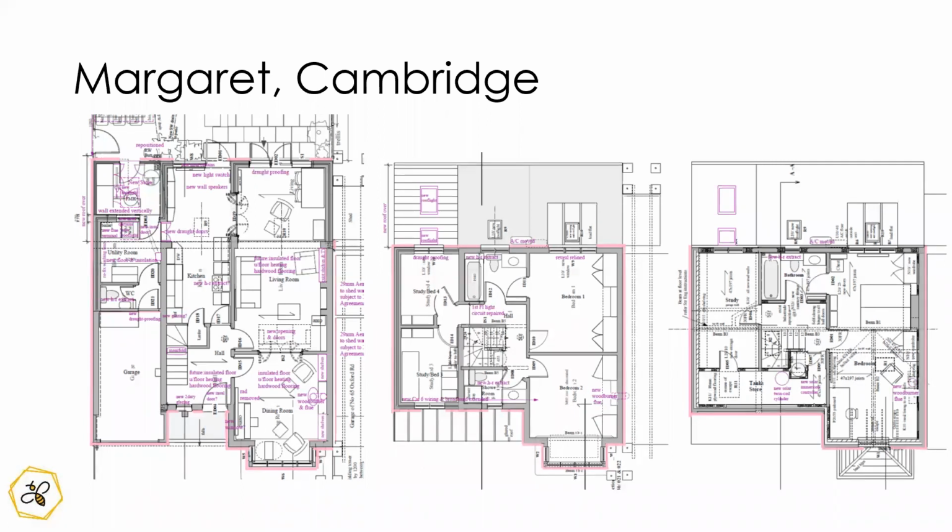And there is evidence from BRE that your heat pump will work more efficiently if you use electric radiators than if you oversize it to account for going down to -5 or further. So I think there's a lot of negotiating to be done here about just how much heat loss there is and how big a heat pump we want. That's right, because I would think you could get down to a 10 kilowatt heat pump or less, depending on what that actual figure is.